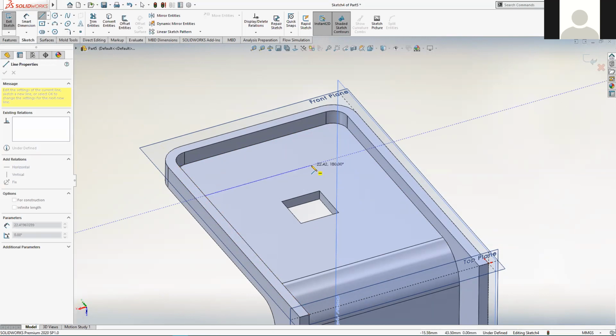Then this is where it becomes a bit difficult. If you are sketching from an isometric view, like we are doing now, sort of 3D viewpoint, the system is giving me that horizontal relation icon, so it's telling me the line is currently horizontal. It's hard to tell that for sure from the view. It may be slightly deceptive, and I may think, oh, well, that looks more or less horizontal. Why is it not?